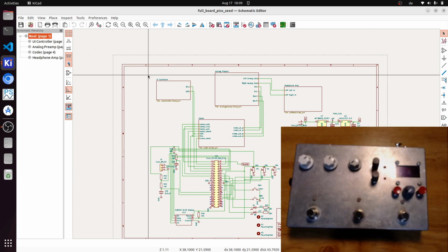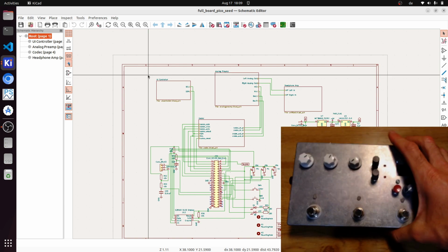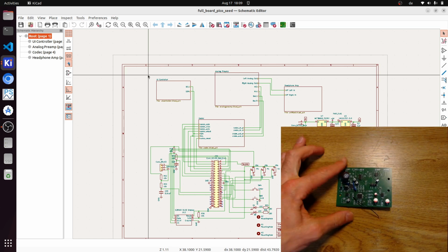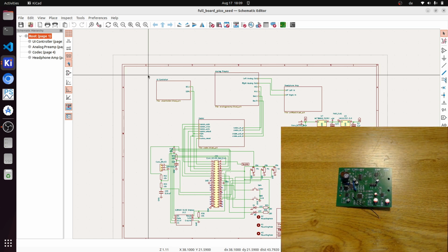So, and for this board, this required a few more connections to make, or a few extensions. I built another PCB, which is this one, which I dubbed extension board, and this allowed to connect the foot switches and to have all the symmetric ins and outs and so on, and also a little EEPROM to save presets, and an additional microprocessor to handle the stomp switches and so on, to talk with the Raspberry Pi Pico.